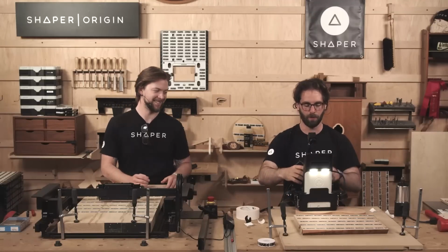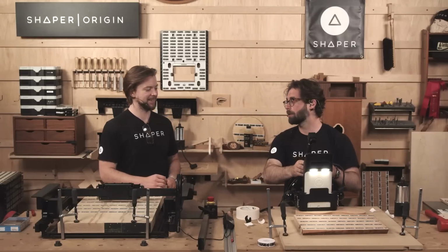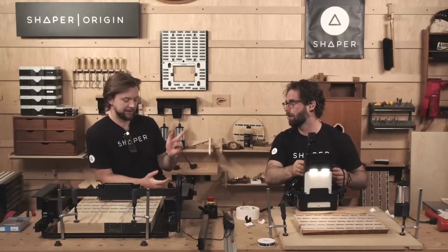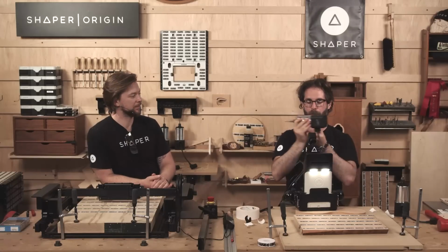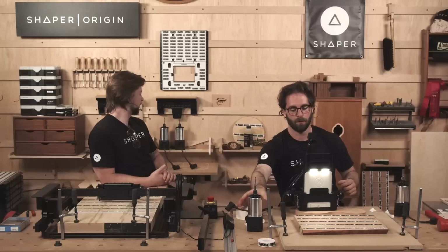Okay, and first thing I want to do before I move the tool at all, in case I forget and turn the spindle on. I think it was smart. I actually just noticed you put this in, but you didn't plug it in. That's a good one, too. Double safety check. So we're going to pull this spindle out so that we don't accidentally turn that on.